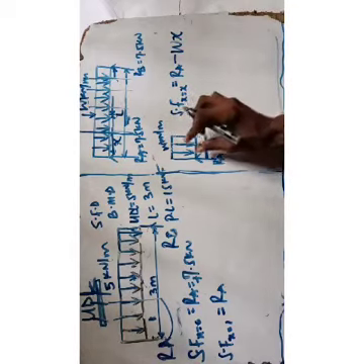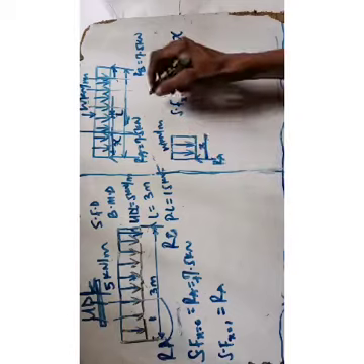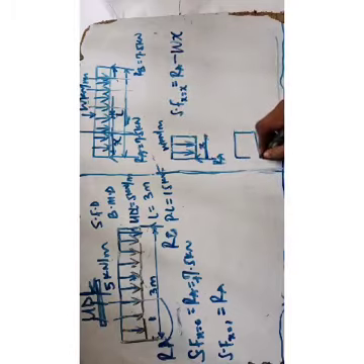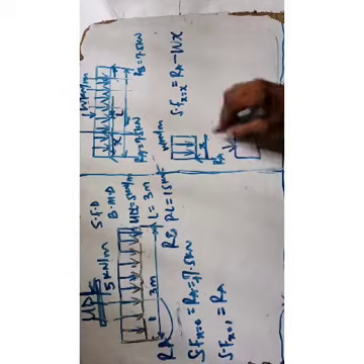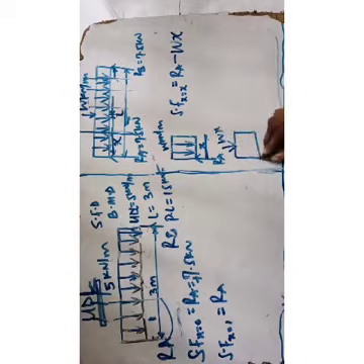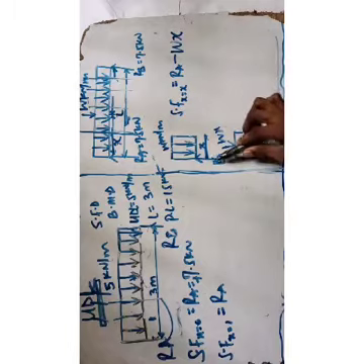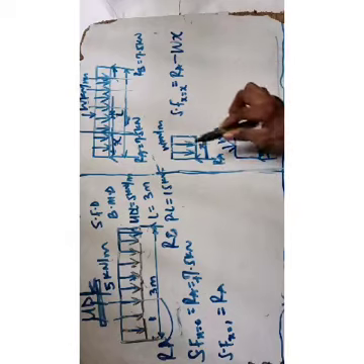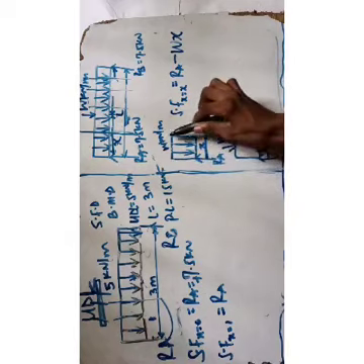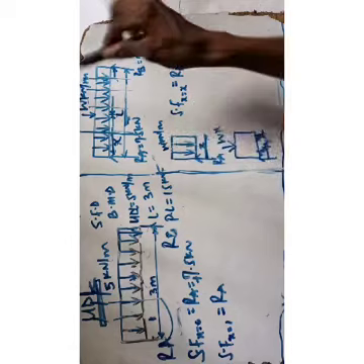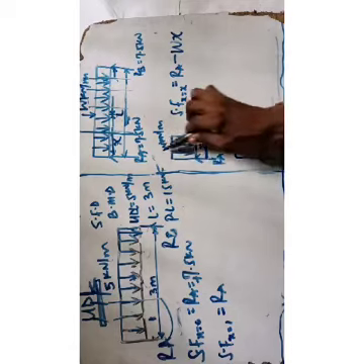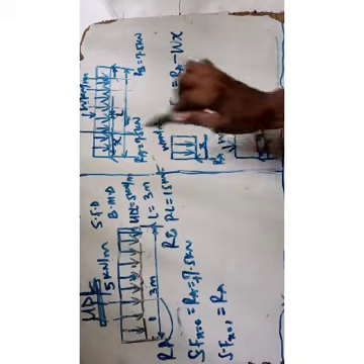Then once you do this, it will change to point load, and the diagram will look like this. So it will act at the center automatically. That is WX. Then you have your RA, and you have the X. And here you have the X at the center, as X over 2, X over 2. So when you take this RA minus, that is clockwise minus anticlockwise, that will be RA minus this W. You convert to point load, that is W times X, length times breadth.